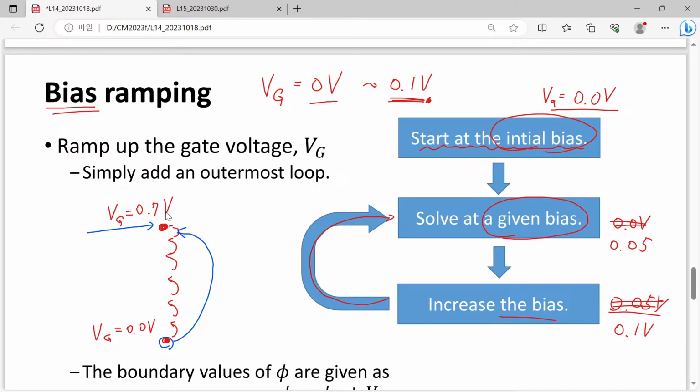But unfortunately, in many cases, approaches like starting directly from a highly turned-on inverted channel, or increasing your bias quite significantly, do not converge. You fail to get the solution. That's why we have slow approaches like this: slightly increasing, and if we succeed, slightly increasing once again.